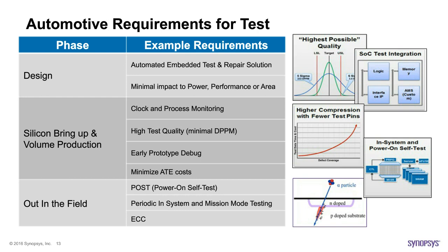It will continue for periodic tests during the mission mode operation, and also doing corrections during mission mode operation. And the reason we do it all in the field as well is because we do have failures that happen in the field. There are permanent types of failures that need this periodic test, and there are transient types of failures, such as soft errors, that will need self-correction and so on. So for these two types of failures, field-oriented testing is a necessity.